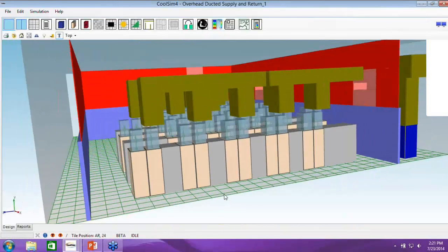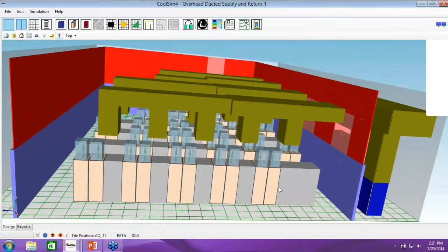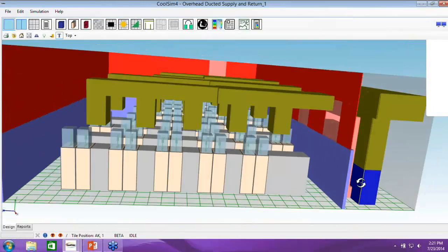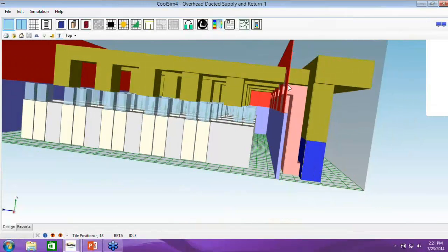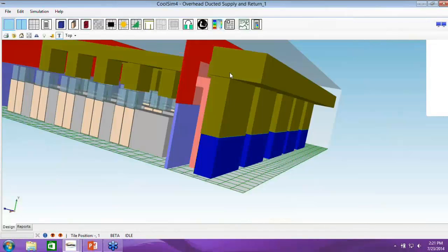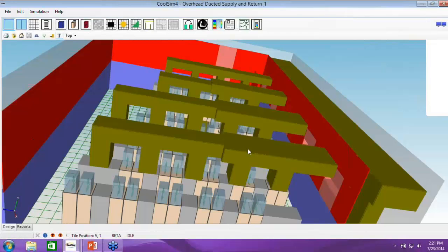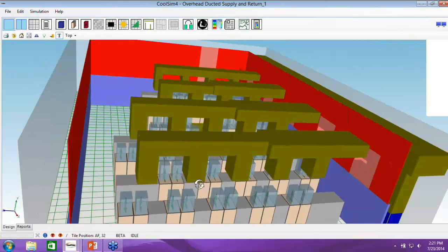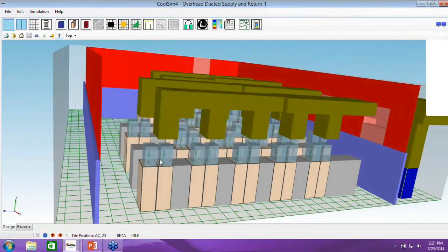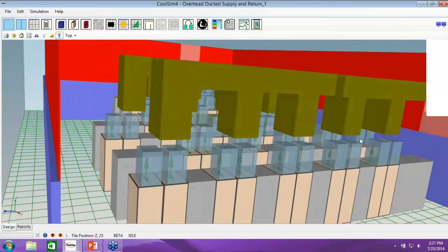And he built this model, a very, very nice, very intricate model. You see here, this one, Magnus, is ducted supply. These are upflows. So the hot air is coming back, being pulled through these ducts into a classical upflow cooling unit, and it's being piped up into a big header and then supplied to this series of subducts and then down into the cold aisle. Sometimes they call these designs a bathtub design, because you're pouring into a bathtub, the cold aisle.